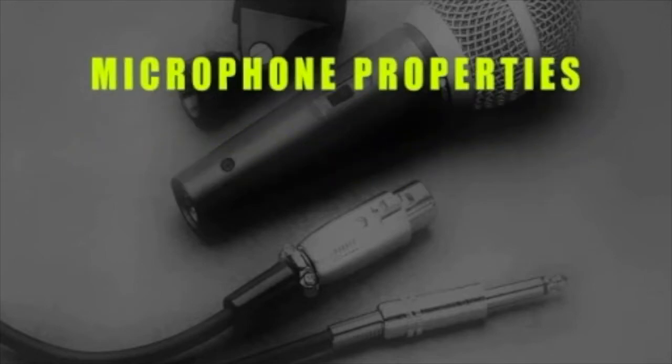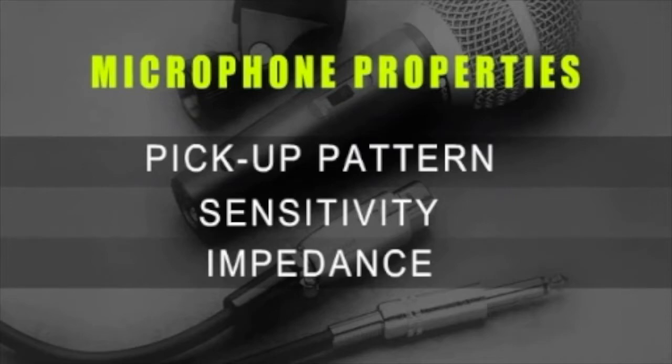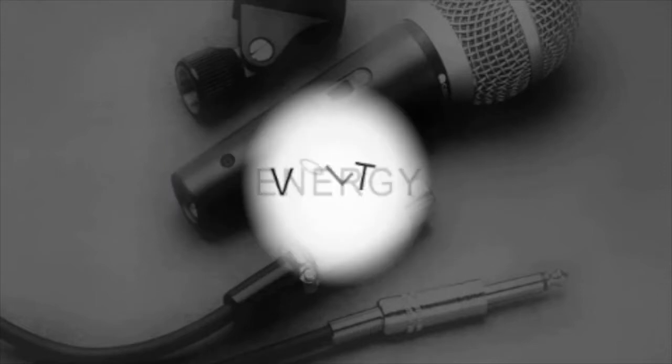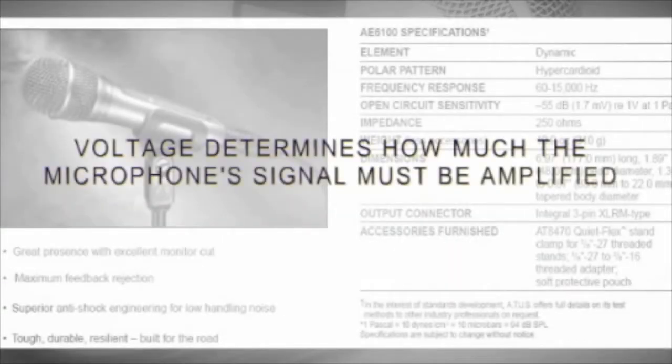Microphones' properties include pickup pattern, sensitivity, and impedance. A microphone's sensitivity is the amount of output energy, measured in volts, the mic will produce using a standard input signal level. This voltage determines how much the microphone signal must be amplified to reach line level.